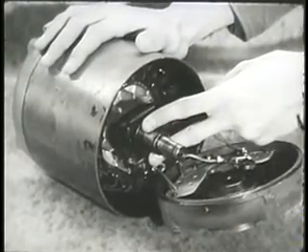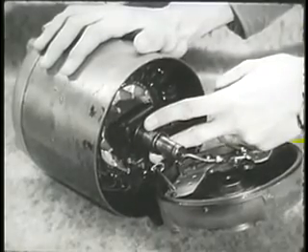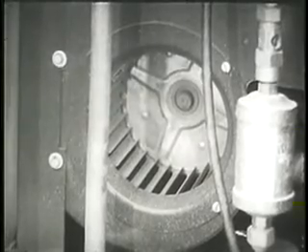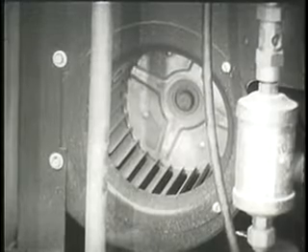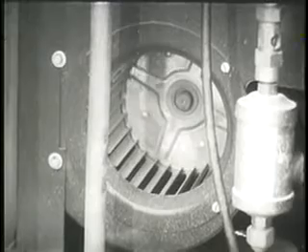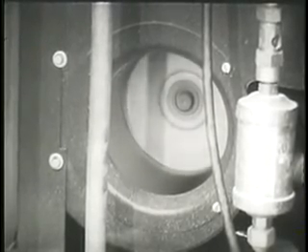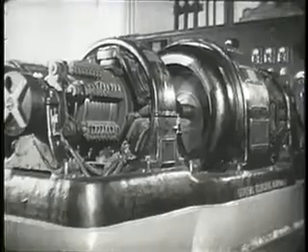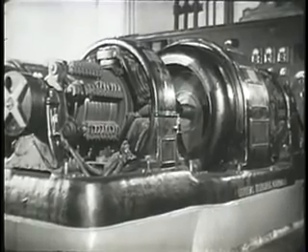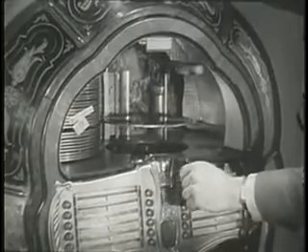The centrifugal switch is mounted on the rotor shaft and is the type used on most split-phase motors. Since the greatest phase shift and relative motion is caused by the capacitor start method, it is used in situations where good starting torque is an important consideration. Among the principal types of AC motors in use, the synchronous motor is used in situations where constant running speed is the governing factor.